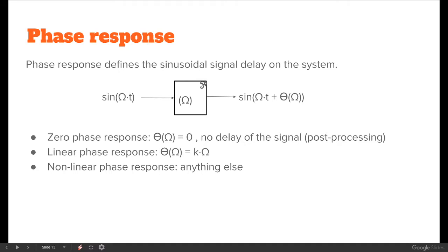For pulse kind of signals, you usually like to use the Bessel filter for almost linear phase. But in the digital domain, you can make the phase response totally linear. This requires a little bit of explanation.